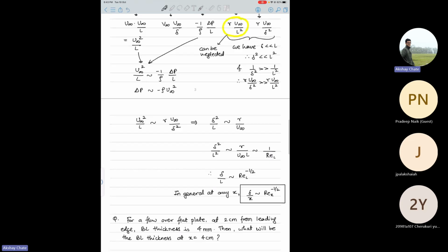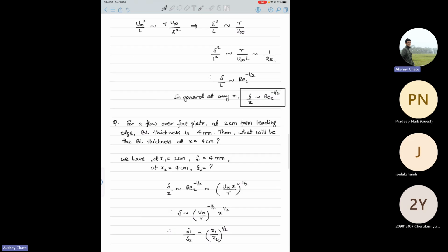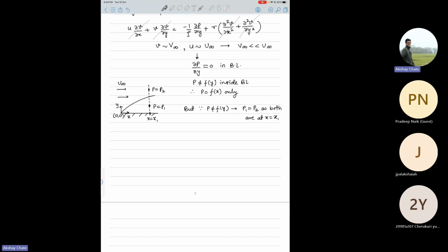And what was the point that I tried to make? Yes, so again, P1 and P2 are equal, right? But the pressure at P2, that point, is in the inviscid region. So this is the inviscid region, right? In the inviscid region, Bernoulli's equation is valid, that we studied earlier. So from there you get P∞ plus ρ U∞² by 2, equal to constant. I'm neglecting the z, assuming a horizontal streamline.